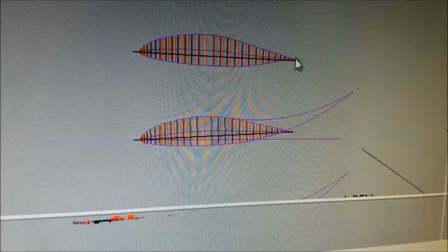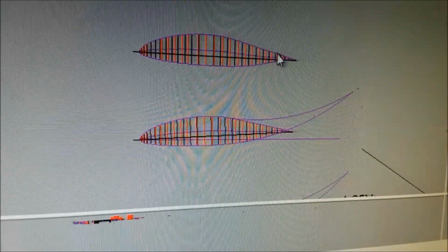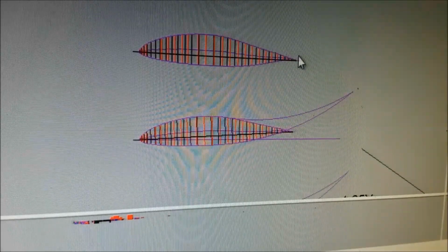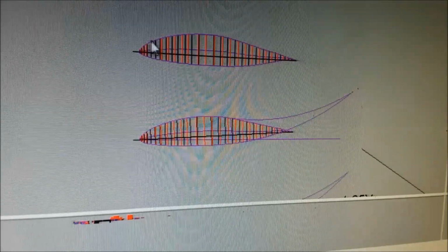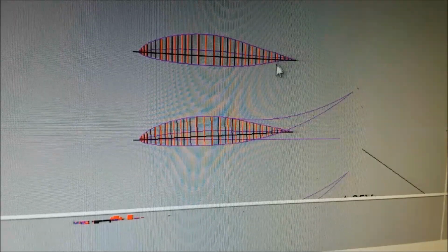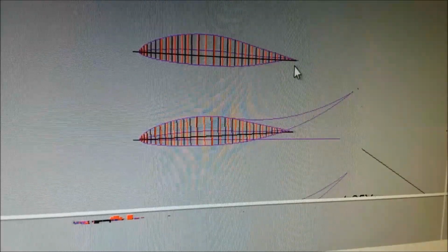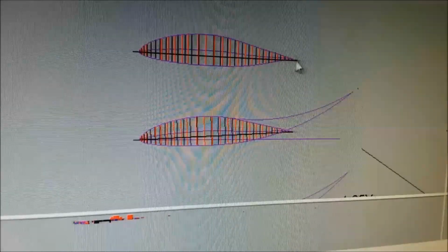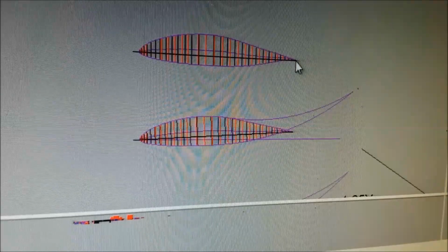If you try to cut your foam, there's nothing holding the back end together. You can't wrap fiberglass around a real sharp corner. It'll pop up, make an air pocket as soon as you walk away from it. But you can run it out here around the front and then do the bottom half, and just shape that to where it'll go up and lay against this other fiberglass you've already made, and then fill in the difference. It takes about an inch space here to get enough thickness, an inch from the trailing edge. And then you just cut off a straight line back here when you're done, because it'll be sloppy as a devil.